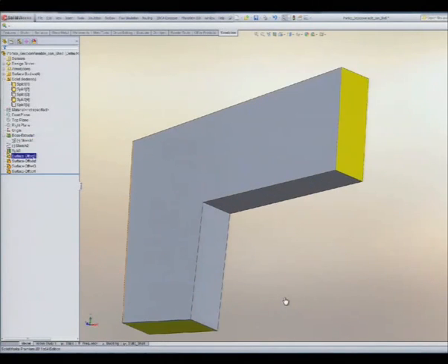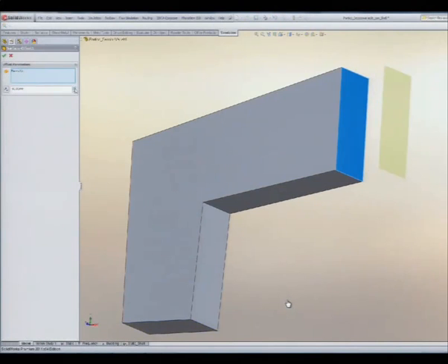And this is the explanation. This is a multi-body part, right? To answer your question, what you see now is a dummy surface that we have to include. We must include this surface as the interface between the solid and the beam. At the very beginning, when I ran my first analysis, I didn't do that. So SolidWorks simulation works as well, but the results are not useful.